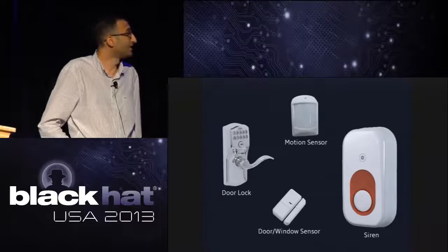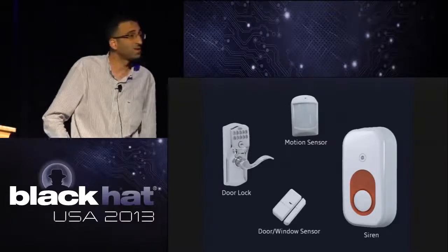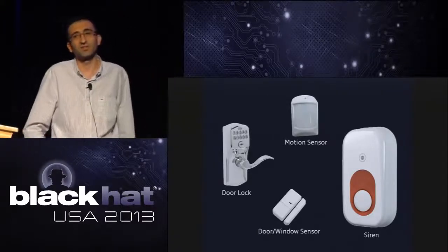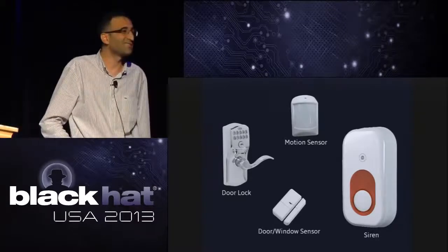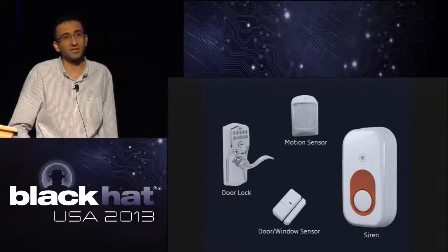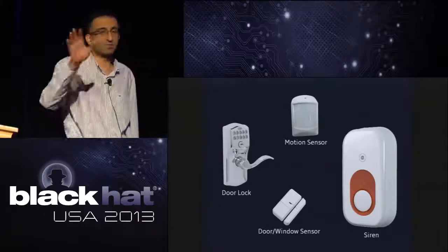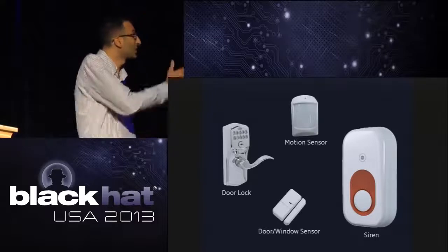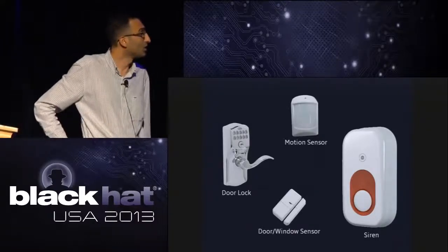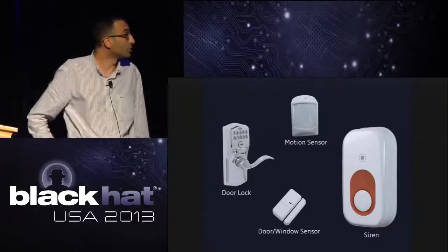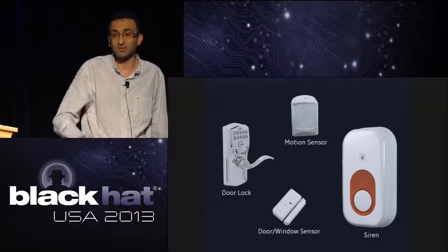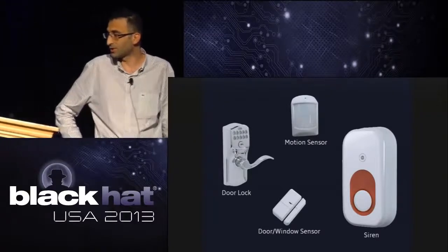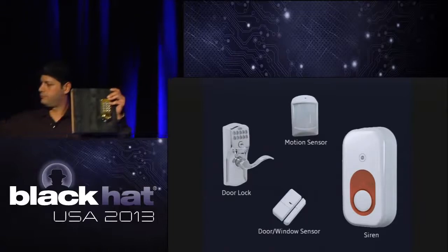And finally, we have the different devices, sensors, and modules. These small devices are mostly battery powered, and each of them has a tiny Z-Wave or Zigbee radio chip running the protocol stack, which allows them to communicate with the central panel as well as with other devices. For instance, you can pair a motion sensor with a siren in order to activate the siren automatically in the event of any movements. So we have two of these devices here, one secure AES encrypted Z-Wave door lock and another motion sensor.